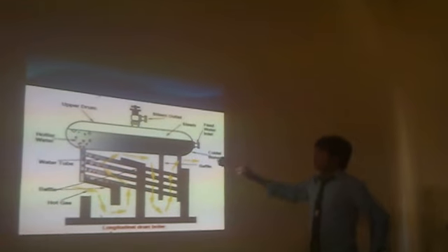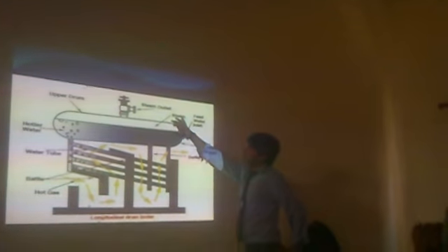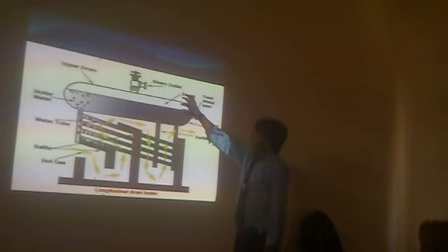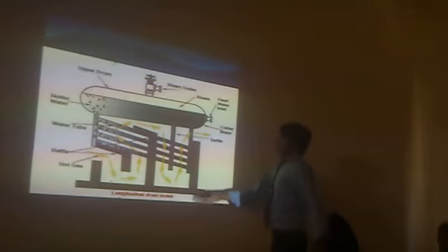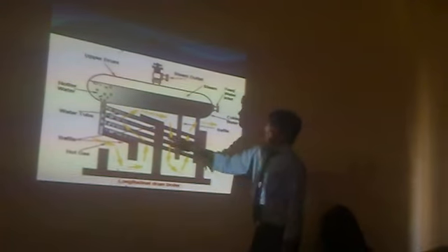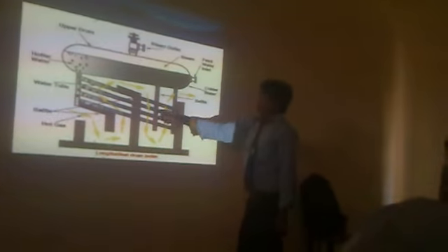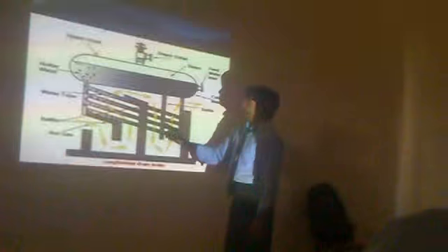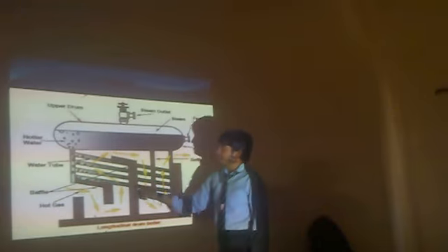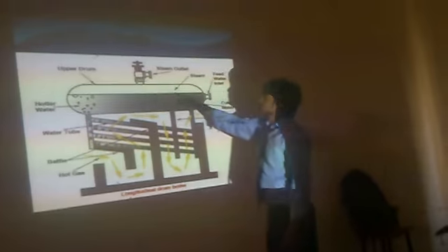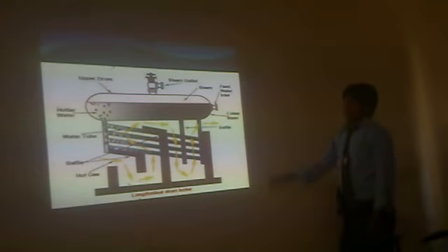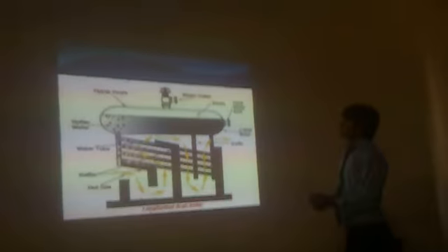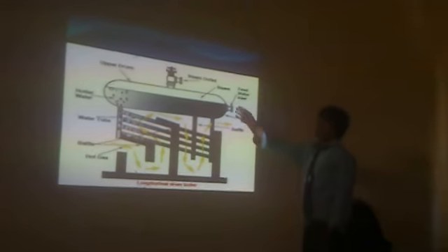This is the inside of the boiler, you can see. This is the steam drum. It is half filled, and the other half is kept as space. Here, in the upper half, the steam is going to be stored. When the coal burns, the boiler is filled with distilled water, and when the water is heated, bubbles are formed, and that is steam formation. Then when high pressure is created, it is sent to the turbine, and there is also a safety valve... no, here it is not the safety valve, it is the feed water pump.